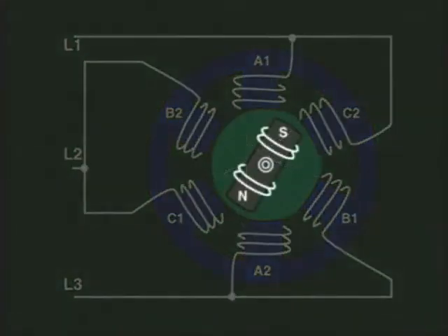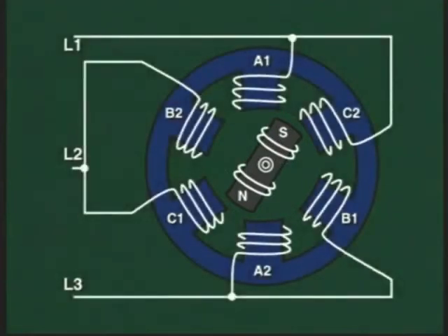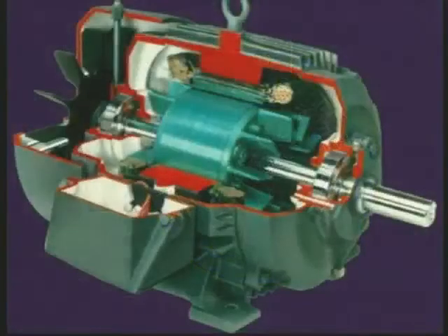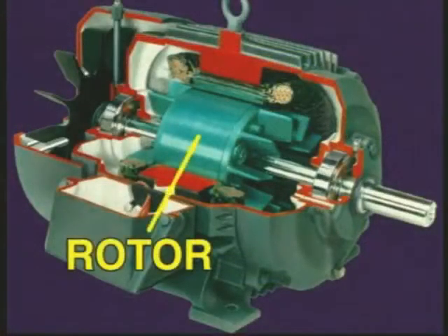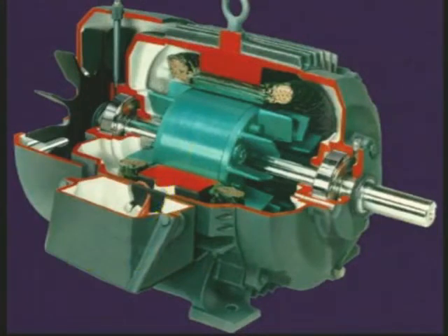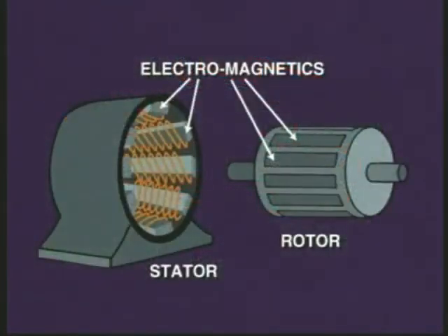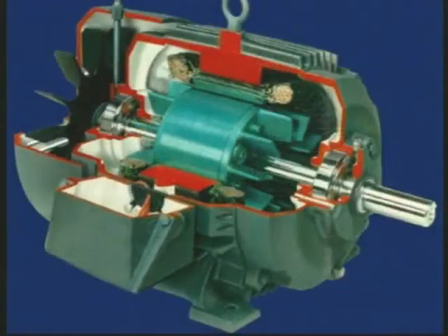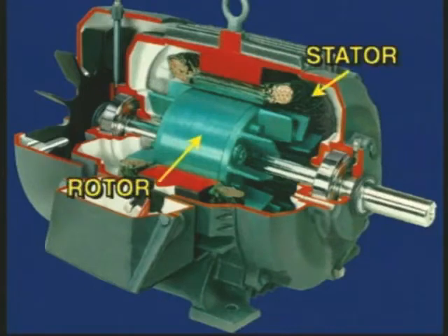The rotor, as its name implies, is the rotating part of the motor and is constructed from either coils of wire wound on laminated steel, or it can be made from all laminated steel without any wire coils. If a motor's rotor has wire coils, it is called a wound rotor motor. A laminated motor rotor, which is most popular nowadays, is called a squirrel cage motor, because the design resembles the cage used for pet hamsters and the like, and therefore its name. As you can see, there are no brushes to pass current to the rotating parts, as was the case in a DC motor. The current is induced from the stator field to the rotor.